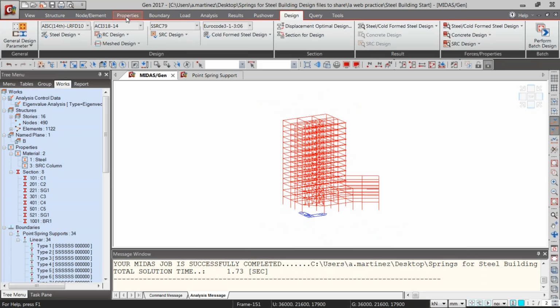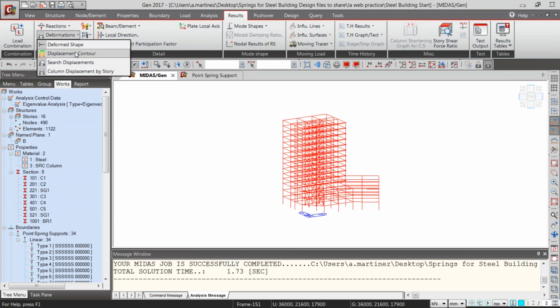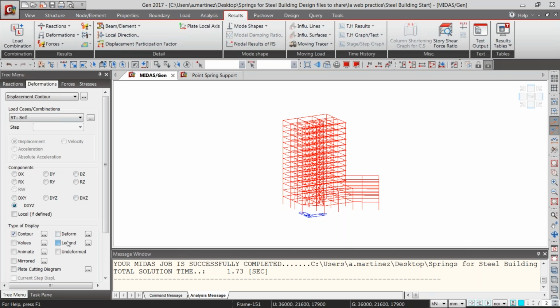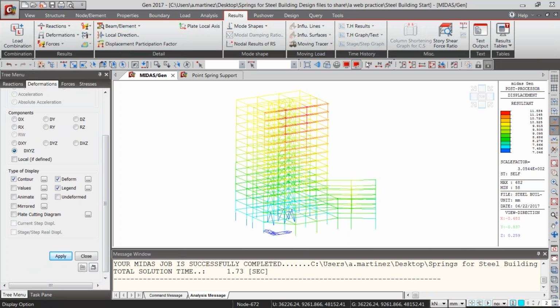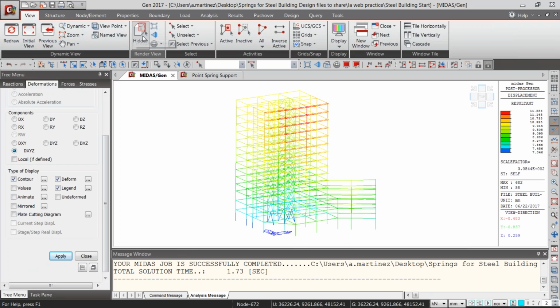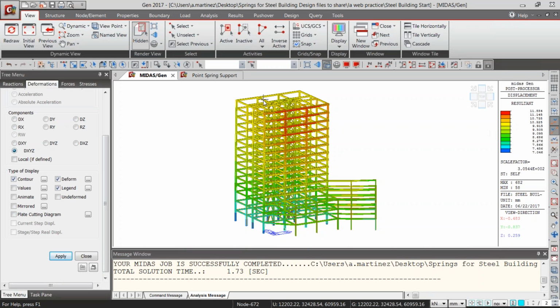So if we were to go back, we've been looking at results like the deformation, the settlement. We could go back one more time and take a look now with the new sections. They're heavier sections, they're bigger sections. And now the structure has a new distribution of deformation. It's now closer to 12 millimeters. So it's gone up a bit, which makes sense since some of our structure sections are now bigger, heavier. And you would also see a new distribution of axial forces, of moments and such.